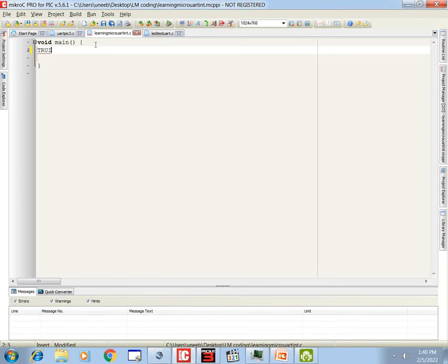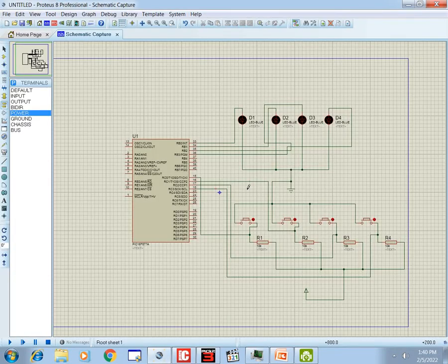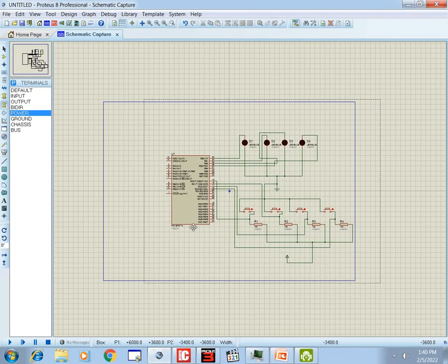Okay, here our programming begins. First we declare our ports. TRISB is equal to 0. We are using port B as output. Initial state must be equal to 0, like all the buttons must be 0. Give an initialization delay of 100. Last thing is we copy this.